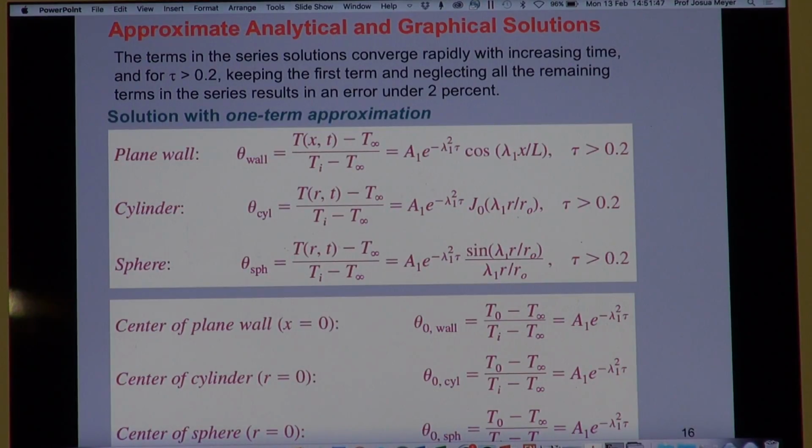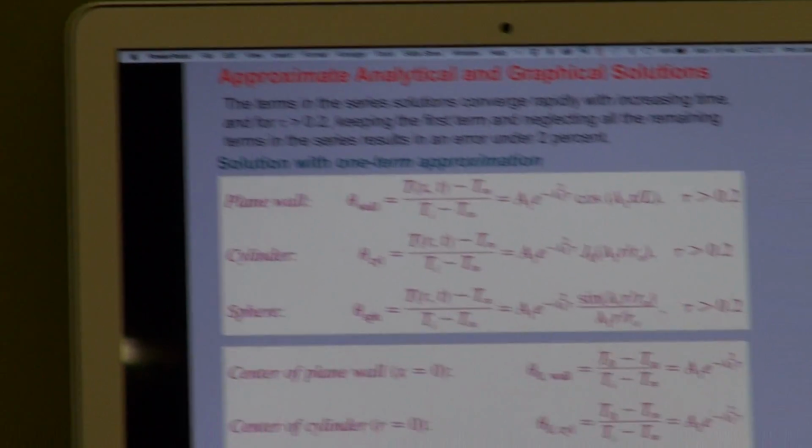So taking that into consideration, it looks quite complicated, but once you've done quite a number of problems, you'll see that in general, you can start solving that if you've got the Biot number. Then you can get very easily, and I will show you just now, all the other variables, and at the end the equation is actually very simple. So let's look at the case for a cylinder.